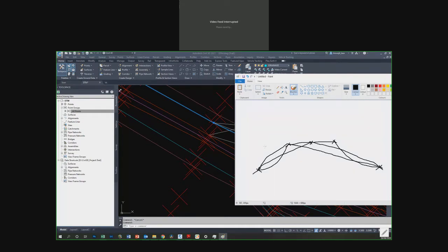Once you triangulate, there are 3 points. These 3 points have a z value, so it will create a plane there. That means on every intersection point you can get a level. Since it is going from, for example, 100 to 98 or whatever it may be, in all these points you will get a level. But physically it shouldn't be like that. You should not get a level on this one.